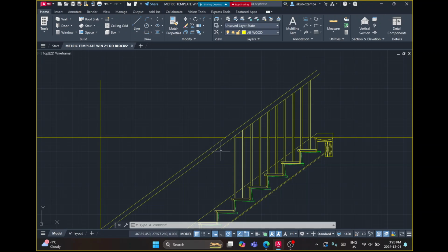So we can do more railing, basically it's the same thing. You would simply keep copying these below, just like you did. To get the horizontal railing above, it's the same procedure. The same distance we copied up here 1,000, you offset up here 1,000, then you just draw more pickets in. So I think you guys got it.